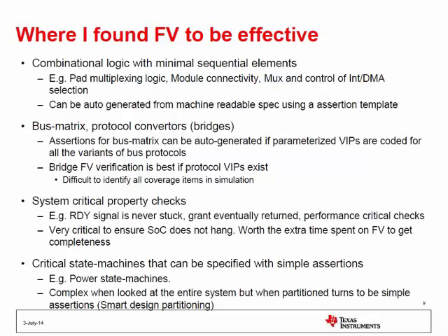The next level is on the bus matrix and protocol conversion, because the bus matrix is, again, something at the SoC level where you see a lot more things being connected. You do have some amount of simulation verification, but if you are buying the bus matrix from a vendor, they already verify it and give it to you. But if you are building it on your own, the advantage of the bus matrix is the protocols are all the same. It is not going to be changing from one side to another. It's the same protocol, and once you develop one VIP which is parameterizable, you can apply it across all the masters and slaves and make sure they are hooked up properly, and you will be able to catch very interesting issues there.